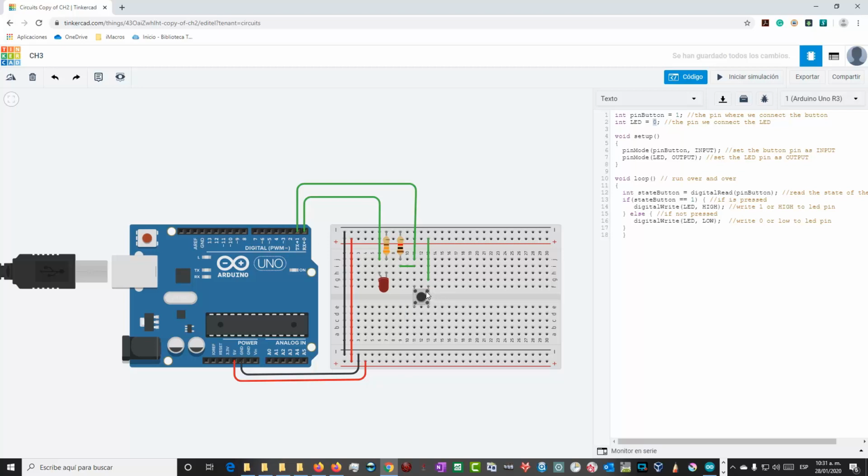And when I don't push this button and I have electrons moving around in the air, and these electrons get in this connection, there is a bigger resistance in here because this is not working, so these floating electrons go to this, and so this is the way to ensure a 0 value when I am not pushing this button.